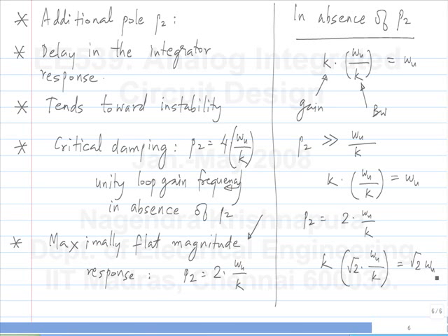Now, this is what I meant by specification of high speed op amps. Now, an op amp, as you know, can be used with any feedback factor above a certain value, right. If you look at the specification of an op amp, it says that it can be used for unity gain feedback. That means that you can use it for any feedback factor, or it could be used for feedback factors less than half, and so on, okay. Now, for a high speed op amp, at the lowest value of K it will be adjusted to give you this, okay.